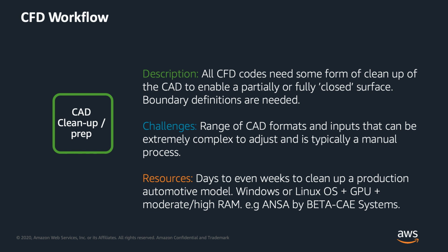Nowadays, software like ANSA by BETA CAE Systems tries to do some of this automatically and greatly improves the speed, but it's still quite an intensive process. This is days to even weeks to clean up a model. Again, it's typically a Windows thing, although some people do also run this on Linux machines. Typically with a GPU, and moderate to high RAM for the most complex models, when you have many parts inside.